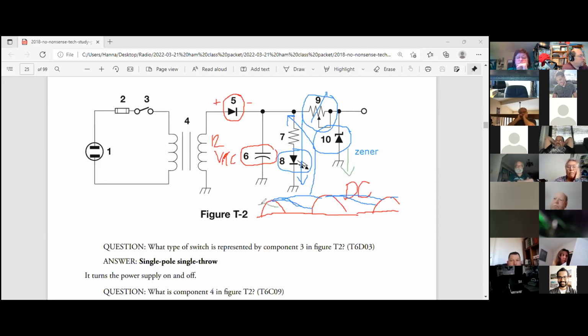Does that make it a voltage regulator? That makes it a voltage regulator. And what comes out of that is a nice, smooth DC voltage. And what do we use nice, smooth DC voltages for? Electronics, because electronics hate voltages that go up and down. So if I were to take this and rip this power supply apart, I would find that this had a couple of diodes in it, probably an integrated circuit, and it would basically work in that fashion. It probably has some really big capacitors in it to smooth things out.